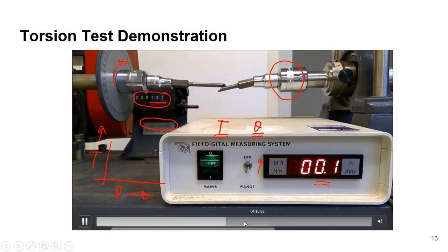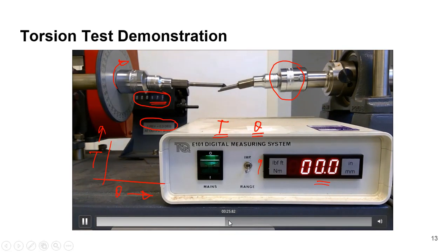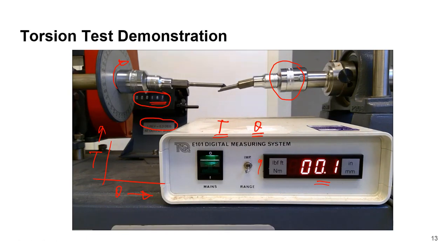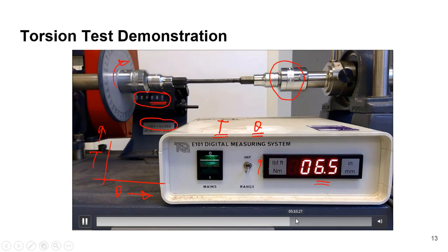Now let me show you. Here you see that this material is a brittle material that was taken, and you can see in this brittle material the fracture under torsion is taking place at an angle of 45 degrees. Now if we take a ductile material, you will find that there is a lot of plastic deformation, and finally you see the fracture that is taking place at that location, if you look carefully, which is perpendicular. So let us try to see why this has happened.